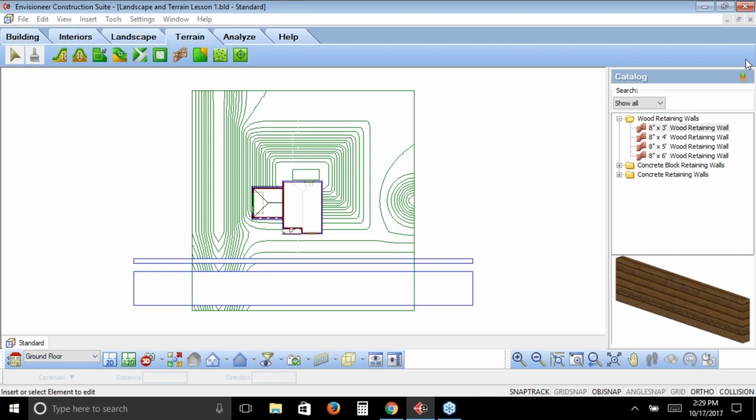Can you use the slope tool and then turn on the spot points to make further adjustments? No. What happens when you use the slope tool, use all of these various tools here, and then go to change it to use spot points, that little dialog box that pops up tells you that it's going to change it to a tin mesh.